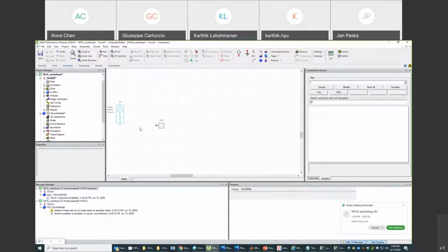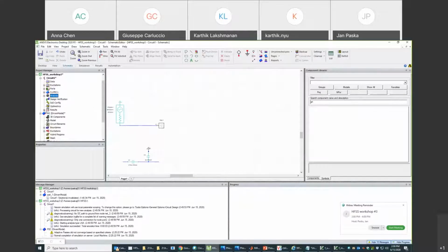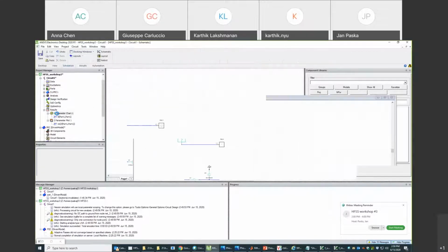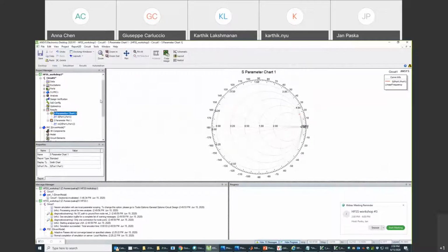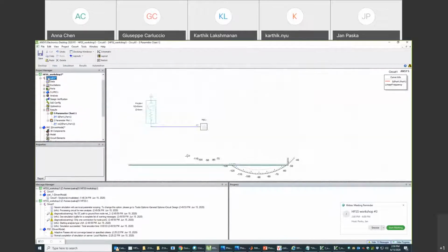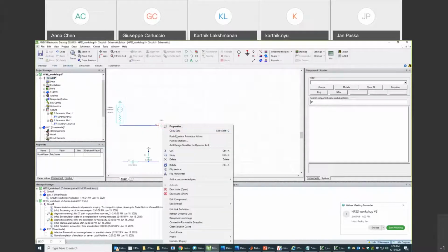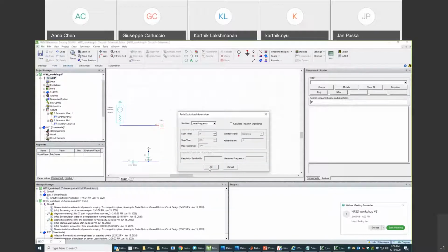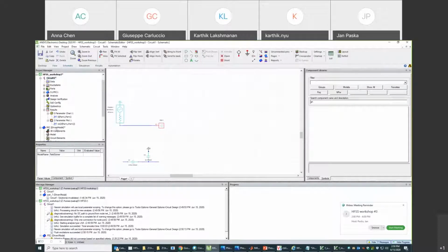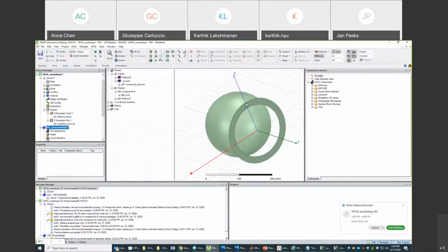Okay, let's try. Because I don't know how to unpush, I'm just going to reconnect it. We're just going to reconnect the circuit like this. Analyze. Let's double check the S parameters, and we are again at the original. So now we can push the results again. Push excitations. So now we should be back to the original without matching network.